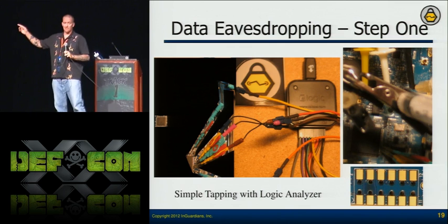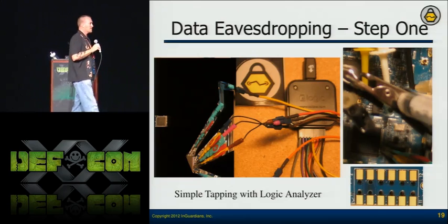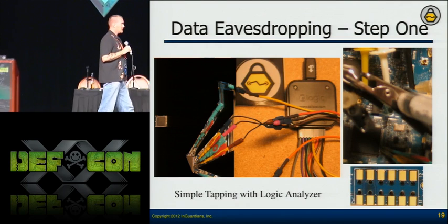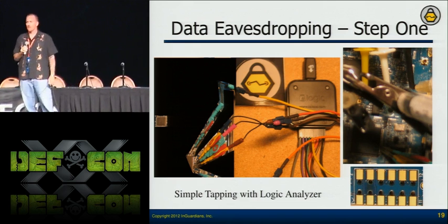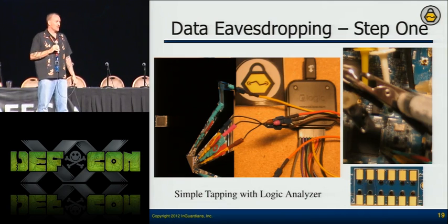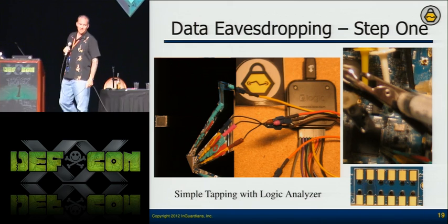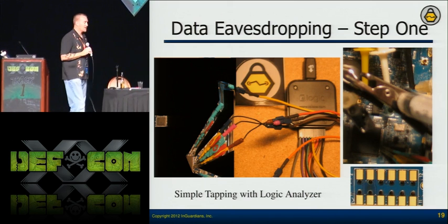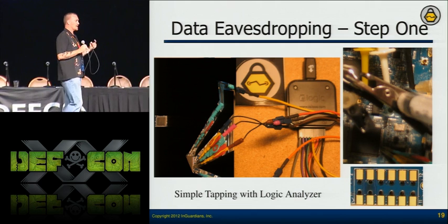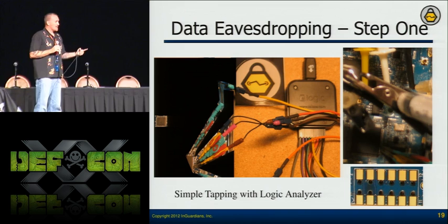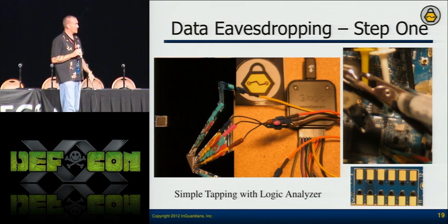Actually, the image that you see right here is the microcontroller driving the radio, which is this really small chip, because the radio doesn't have enough memory to keep that. So the microcontroller has to manage it. It has to send it the next hop, the next hop. Who understands frequency hopping? If you monitor these lines and you save them off to a file, now you have the hopping pattern for that particular radio. Now you can start using that for your analysis into other things like finding patterns, understanding how they're generating that hopping pattern. And if you can do that, now you're getting into the next phase that I really want to get into, and we're already working on that.